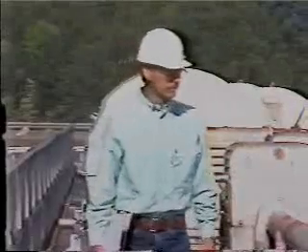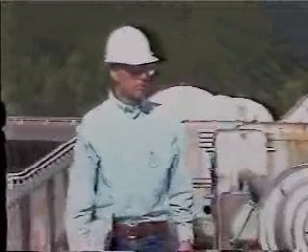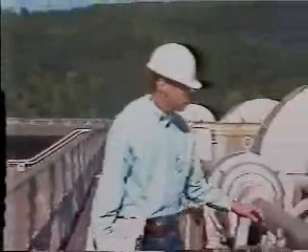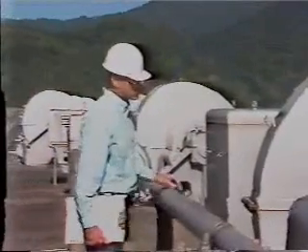In this case, the radial gate has been dewatered for the inspection. This inspection will have two parts: a visual inspection of the hoist and gate, and an on-water test operation of the gate. First, conduct a visual inspection of the hoist equipment. Most radial gates have fixed hoists driven by an electric motor.